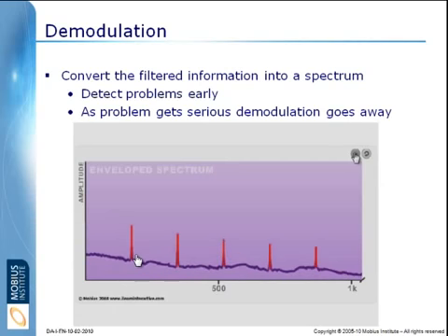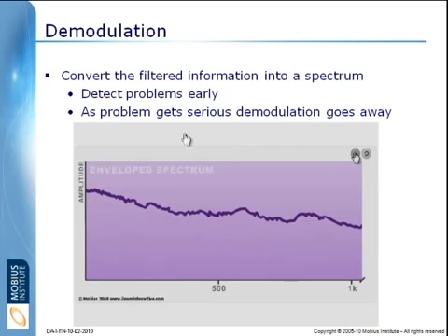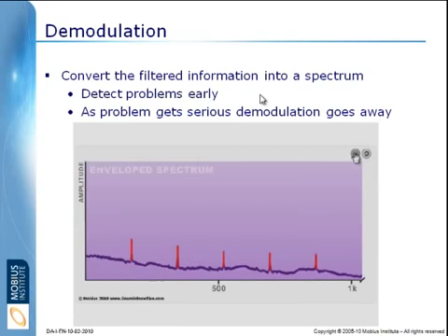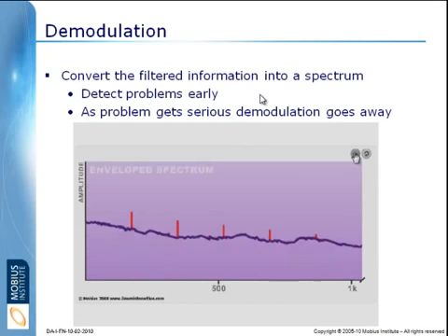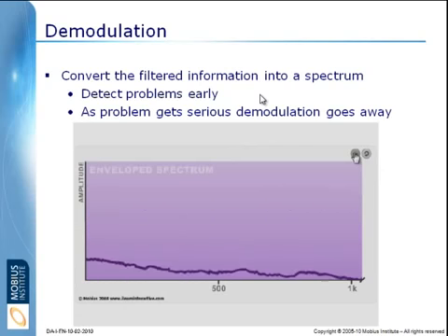That's the rate at which we hear the sound of the bearing happening, or getting hit. And because we've filtered out all the other vibration from the machine, this technique is very, very sensitive. We filter out all the other vibration, and then we can zoom in on the sound of that bearing ringing, and then ask again using filters, what's the rate at which it's getting rung?